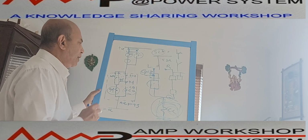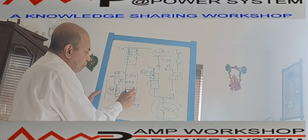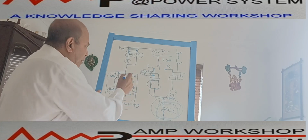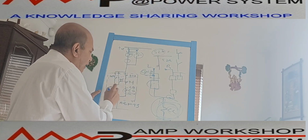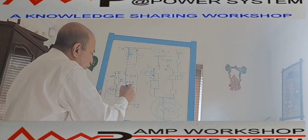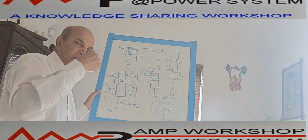So what is happening over here? Suppose we are going to close the breaker, and the breaker is already in open condition. This contact is NC and the relay is not energized, so this is also NC. The moment you give the closing command in the local position, immediately through the interlock, power will come through this closing coil, and it will get energized. The moment the closing coil gets energized, immediately the breaker will close.